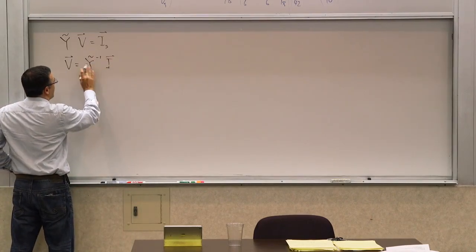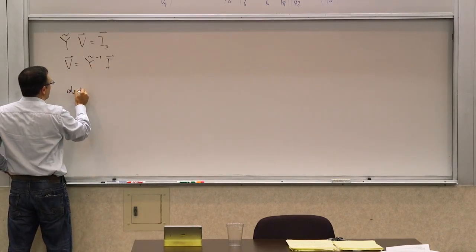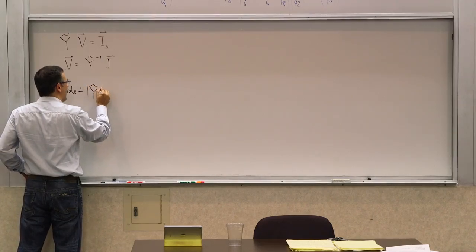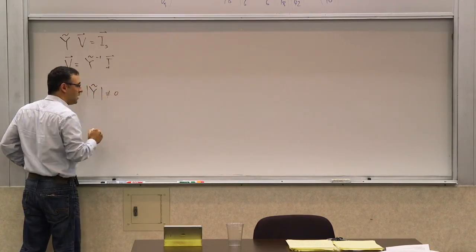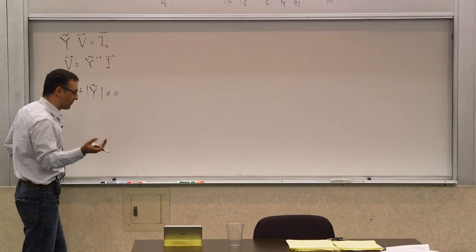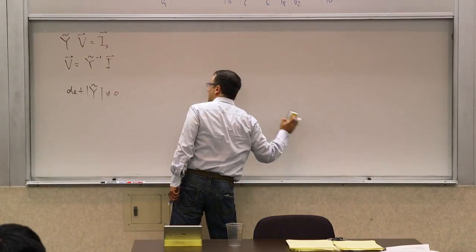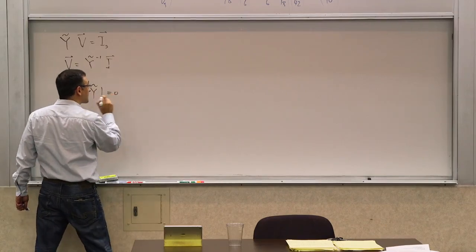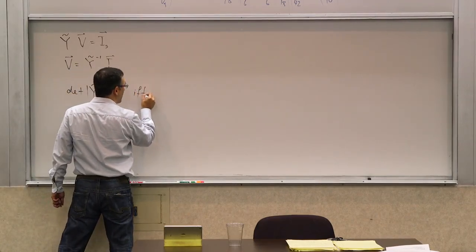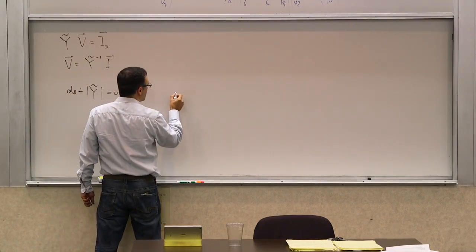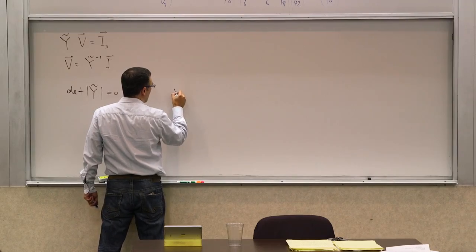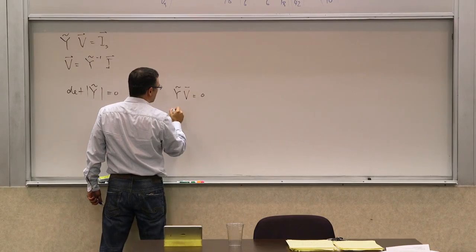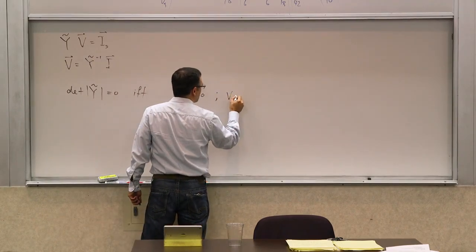So what happens is that obviously if the determinant of Y is non-zero, then you have a solution. But we want to see what it means in the circuit domain. And we saw last time, and I'm just quickly going to remind you, that the determinant is 0 if and only if the only solution for Y times V being 0 is V equals 0.